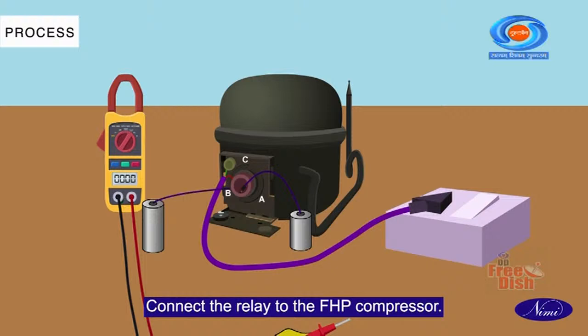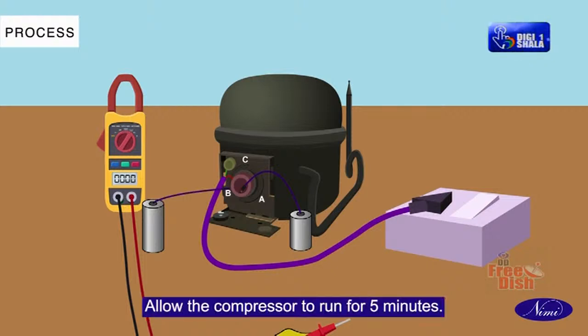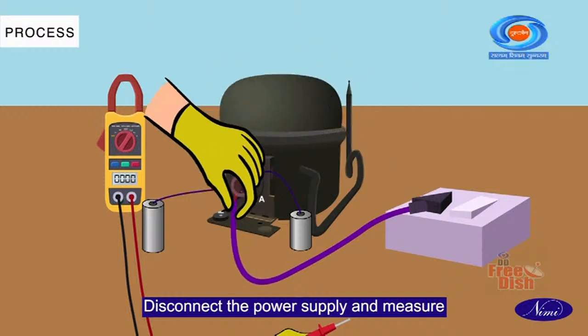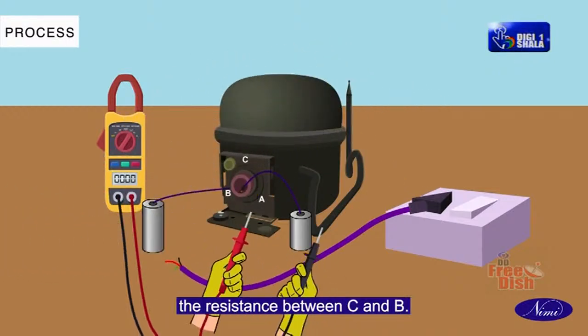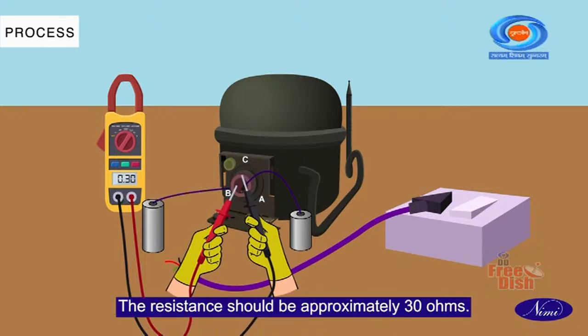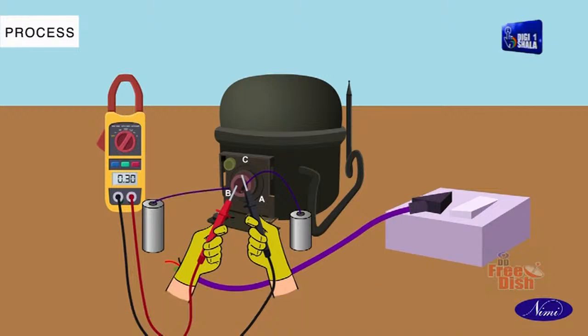Connect the relay to the FHP compressor. Allow the compressor to run for 5 minutes. Disconnect the power supply and measure the resistance between C and B. The resistance should be approximately 30 ohms.